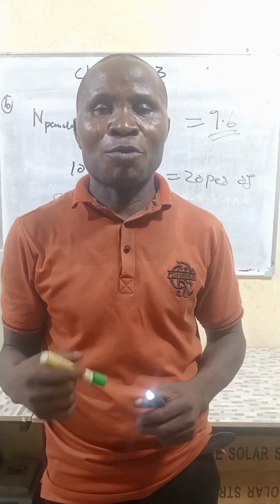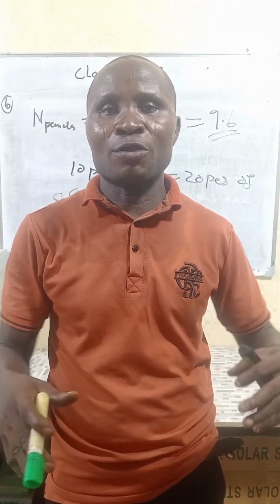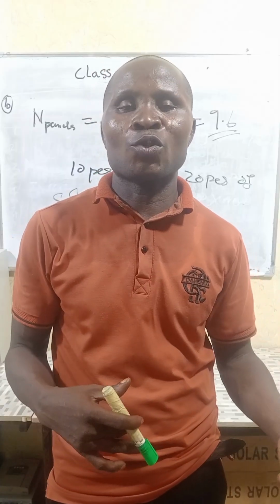Question B, the number of solar panels we needed. This is because of the irradiance of this environment; yours may be different. You can get equipment to test the irradiance around you so that you know whether to multiply by 2, or you can use exactly what your design comes out with.